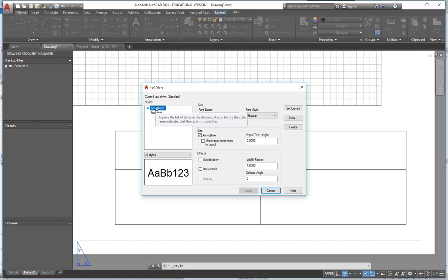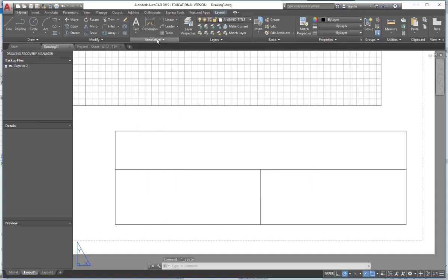Now I'm going to show you both methods, but for now, just use annotative. And if you're drawing on your page, you don't have to scale it anyway. And it's a lot easier, so it's always one-to-one. It's when you're doing it in a viewport that you've got to think about the scaling. And then again, I think annotative makes it much easier, but I'll explain that in more detail later. So for now, just to go through the steps.